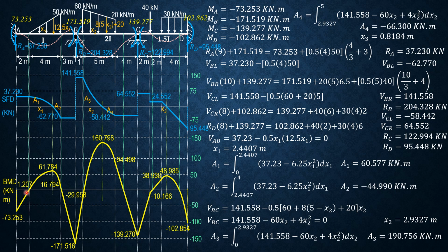Let's have the points of inflection, 0 moments projected upward, where concavity changes direction at these points, here, here, and here. So concave down, horizontal tangent, concave up, concave down, concave up in this portion, positive moment, concave down, then concave up, concave down.